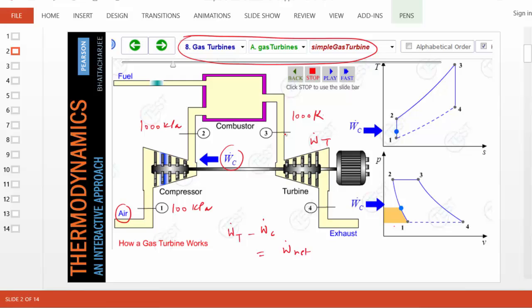In a combustion chamber, when heat is added through the heat release of the combustion of fuel, the pressure doesn't increase. The misconception comes from the fact that whenever we think of what will happen to a gas if I increase the temperature, the instinctive answer is that pressure will increase. That's because in our mind, PV equals RT is kind of ingrained. If temperature increases, and if volume remains constant, then of course pressure will increase. In a closed chamber, volume doesn't change, therefore pressure increases. We just take it as a rule of thumb.